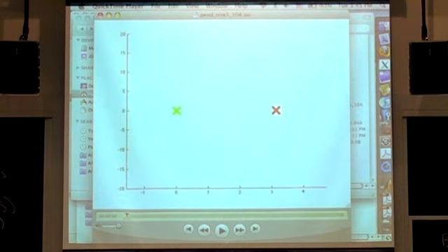Now all I told you so far is I know how to take an LQR problem and try to estimate the basin of attraction. So step one is to take a linearization around my goal state, design an LQR controller, and estimate its basin of attraction. And that looks like this.